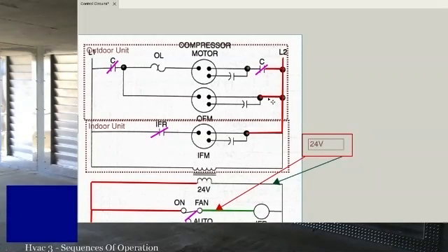And start with residential, unless you do a ton of commercial and you're halfway decent at commercial wiring diagrams and you want to start refining your commercial wiring diagram experience, because commercial gets really hectic really quick, especially on IntelliPacks and things like that. But your Carrier mid-size RTUs are usually pretty dang easy. Your mid-size Trane are not too bad. It's just when you get to 40 tons and up they can get real hectic, or you get into Aeons or McQuays, or VRF. So you don't want to start on that. You don't want to try and tackle a hard one first.